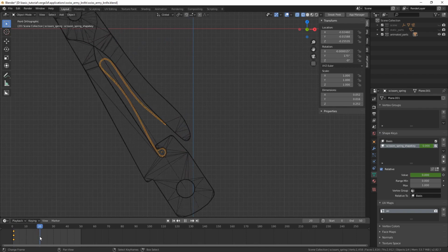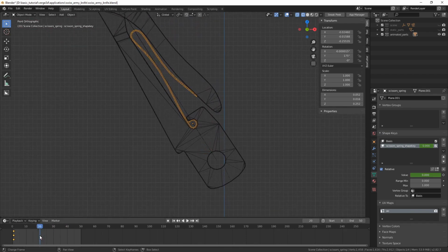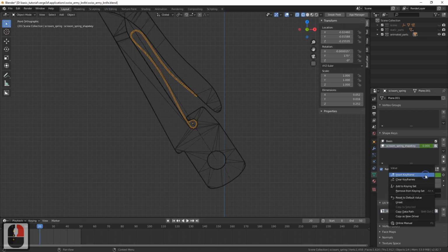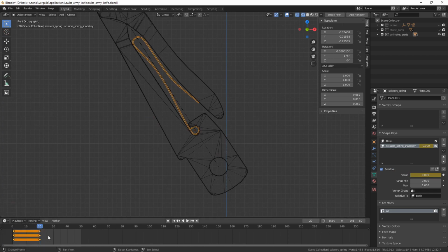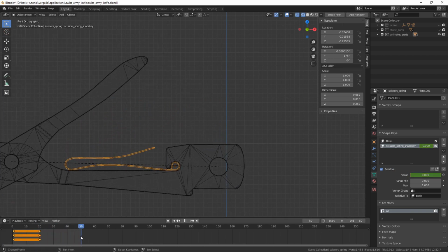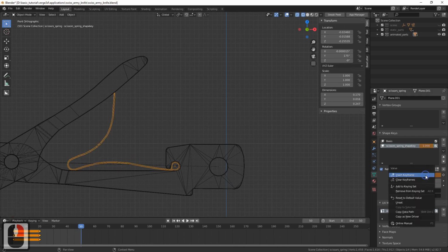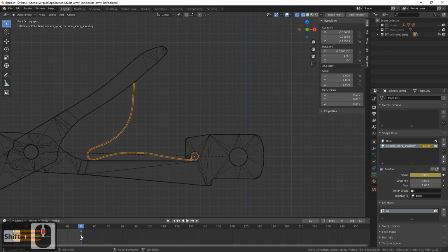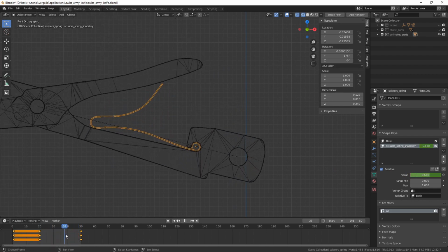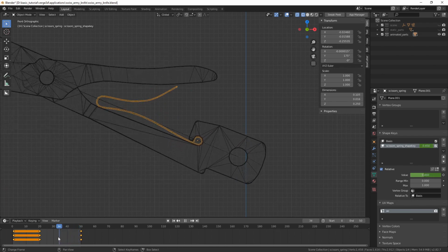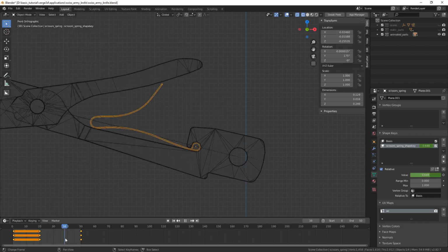Keyframe. There are no changes until frame 20. It's only after frame 20 the scissors begin unfolding, so we should insert another 0 key here. Finally, the animation goes on until frame 50. So we should change the value to 1 and insert a key at frame 50.